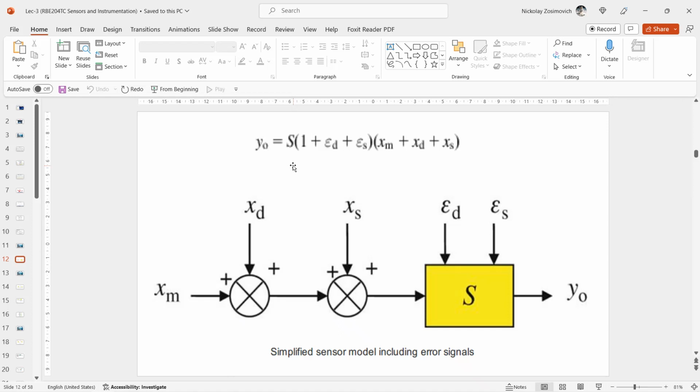Improvement of sensor performance can be obtained through use of a sophisticated design or simply through some additional signal processing. In today's lecture, we discuss five basic error reduction methods: compensation, feedback, filtering, modulation, and correction. The methods apply not only to sensors, but also to other signal handling systems, such as amplifiers and signal transmission systems.